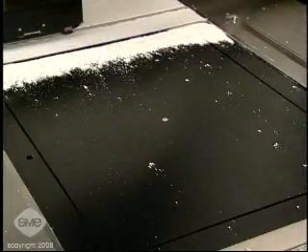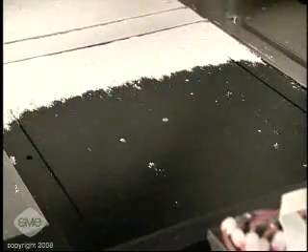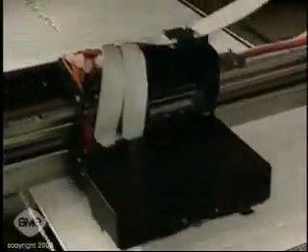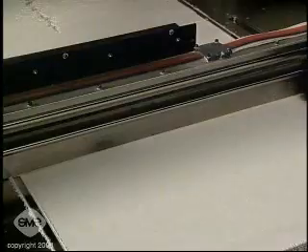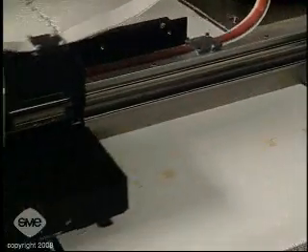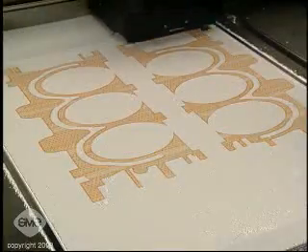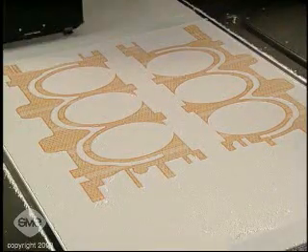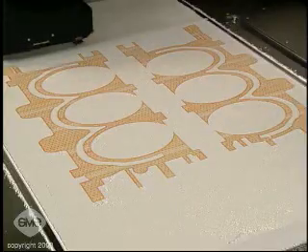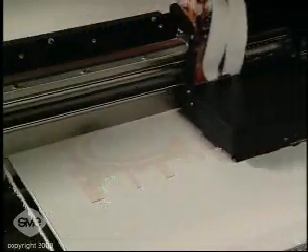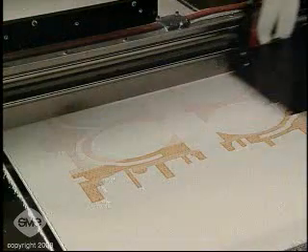The Z810 modeler has a wiper blade that smooths the powder in the build area until it is level. Once level, the powder is infiltrated with a binder from the printer head. The binder is dispensed only in the areas dictated by the CAD file. Once a layer is printed, the platform lowers, and the existing layer is leveled over with powder, and printing resumes. This process is repeated until the model is complete.